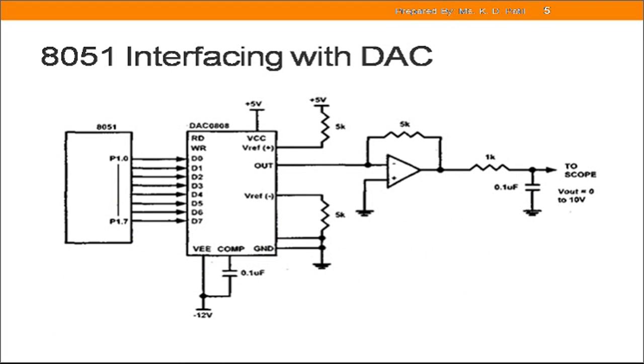Okay, and this current whatever we got here at this output pin, that will be converted into the voltage because digital systems accept those analog signals in the form of voltage. So ideally we connect that output pin to the resistor and convert this current to the voltage and monitor the output at the scope, but it causes inaccuracy since the input resistance of the load where it is connected will also affect the output voltage.